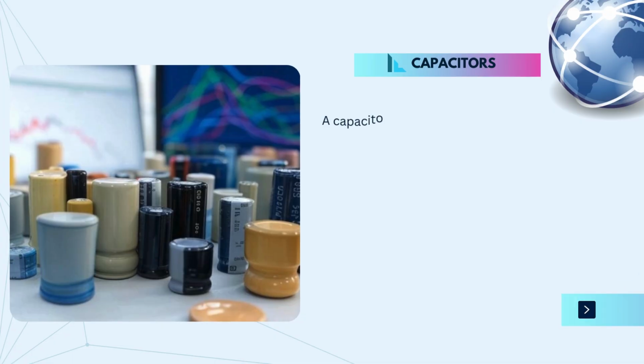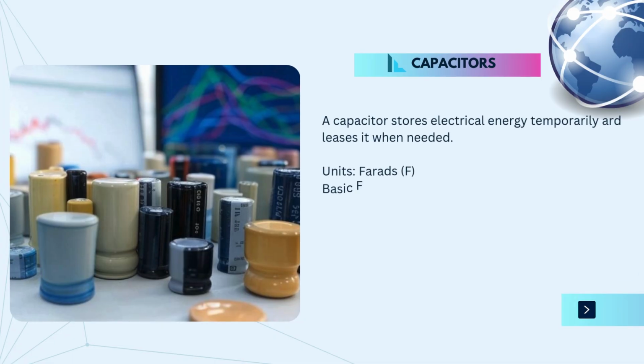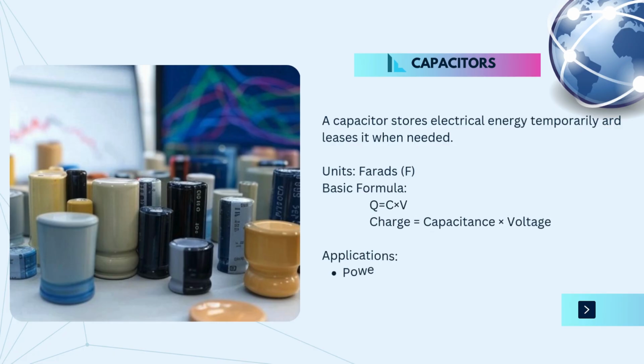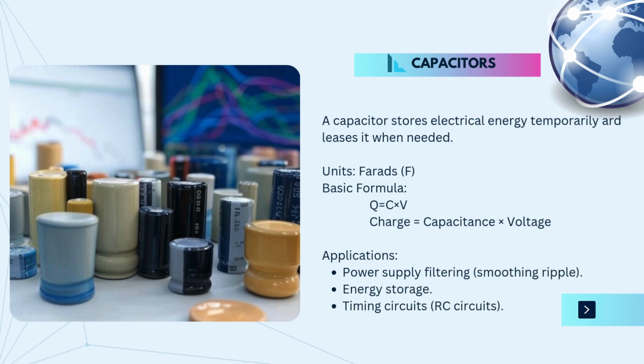Next, we have capacitors. A capacitor stores electrical energy temporarily and releases it when needed. Key points. Units: farads, but often microfarads, nanofarads, or picofarads. Basic formula: Q equals C times V. Charge equals capacitance times voltage.